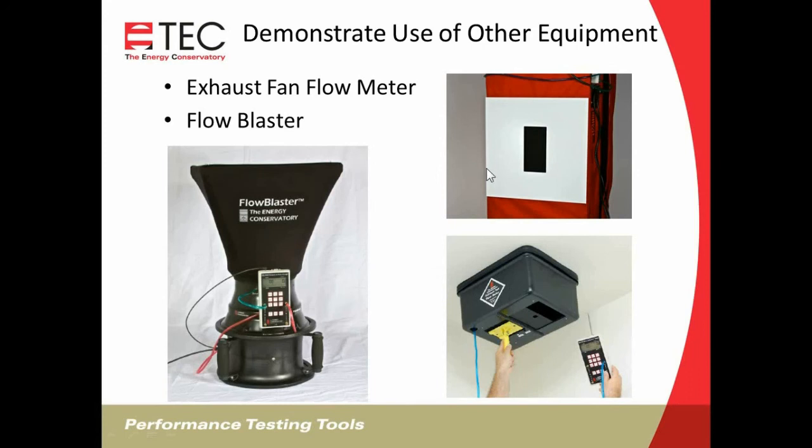The white attachment plate is sized such that you can use it to measure flows, to demonstrate the use of the flow blaster or the exhaust fan flow meter. Just remember, the exhaust fan flow meter is only designed for air going into the fan, measuring exhaust or return flows, and not for measuring supply flows.